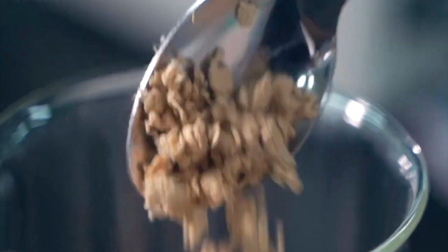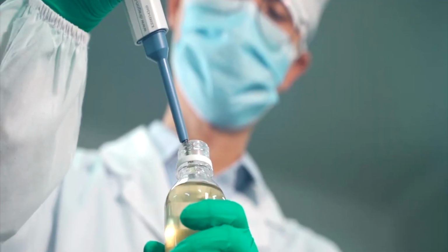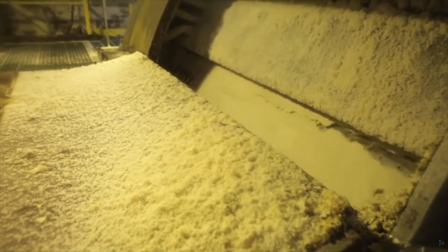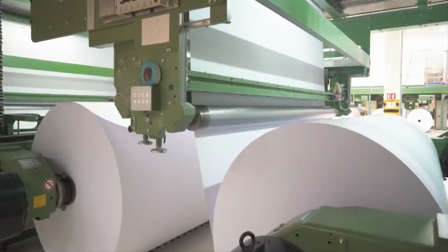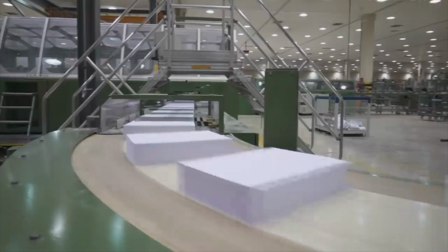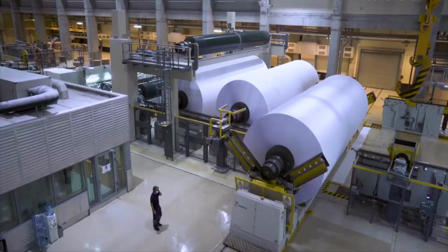The bleaching process involves adding oxidizing chemical agents like chlorine dioxide or hydrogen peroxide to the paper pulp mixture. These chemicals extract residues like lignin that give unbleached papers their natural darker color. Removing these residues increases the paper's ability to reflect light for enhanced brightness and whiteness. The intended application of the final paper product ultimately determines whether performing bleaching is an essential manufacturing step or not.